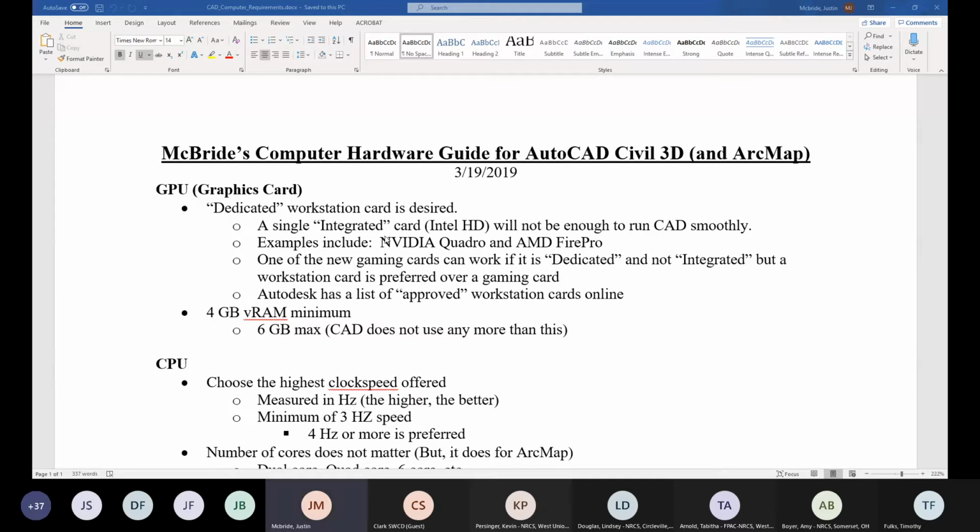That's all I had. Other than for the soil stuff, I don't have access to the clue layer or anything like that. And oftentimes up in Northwest Ohio, your curve number is going to be 85. You can do all the processes like that, but because we're so flat up here with such consistent soil types, it's normally going to be 85 or 86 or 84. So generally we spend less time on that, but that does not give you the green light to use that. You should still use the same process Amy showed, or if you're even better with ArcMap, use the process that Lindsay showed earlier. So that's all I have, Tim.